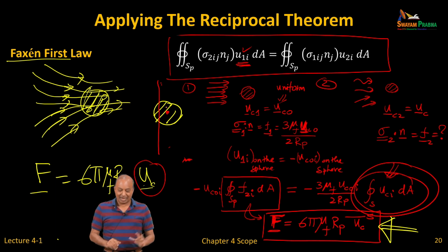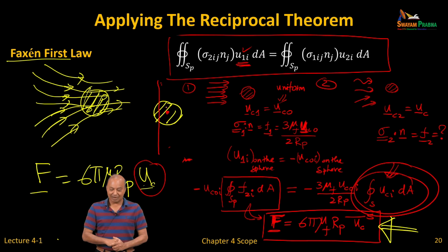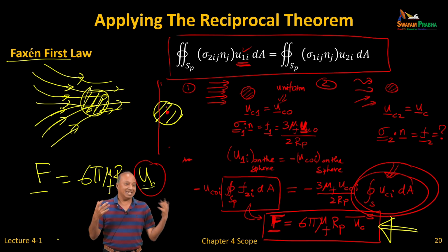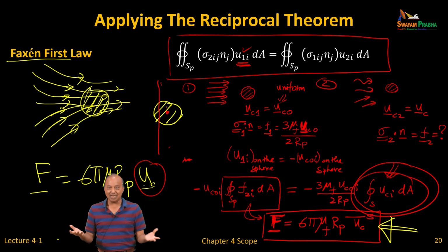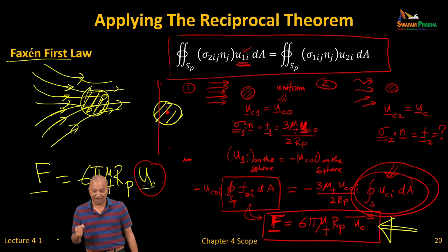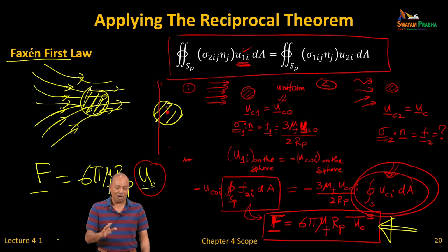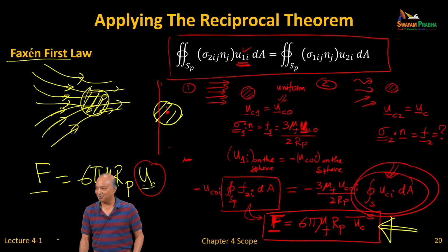So having said that, I have made a case that the undisturbed fluid velocity, I am not talking about the disturbed fluid velocity, in other words the velocity of the fluid in the absence of the particle, could change on the scale of the particle. In which case, Faxen's law won't work for shock-particle interaction, unfortunately, because there the Reynolds number is too large.